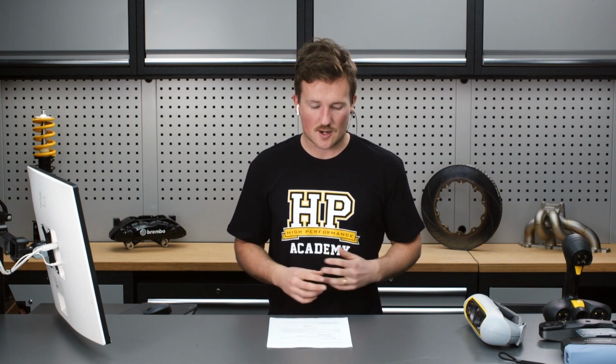For example, with some of the more basic software, you can't take multiple scans of one object and then merge them together. And that makes it really difficult if you've got to scan one side of something and then flip it over and then scan the other side. It's usually best to just do that in 2 scans and then merge them together. And if that's not possible in that scanning software, it can be quite annoying, because you'd have to then go and use a different third-party software to get that job done.